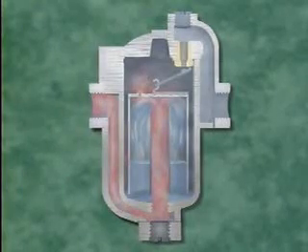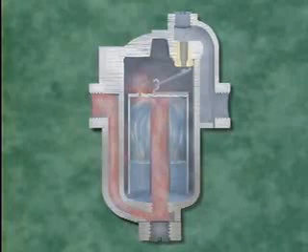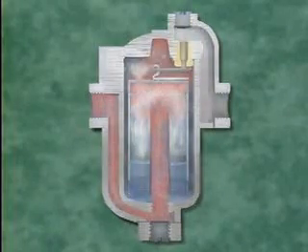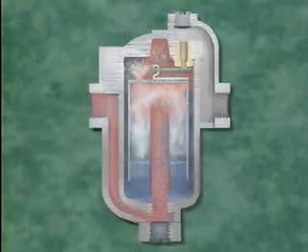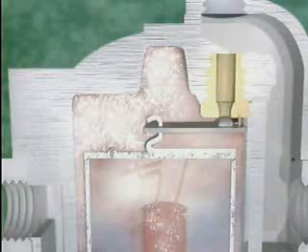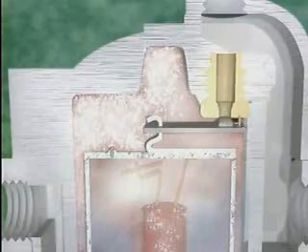When steam enters and accumulates to fill about 2/3 of the bucket, the bucket floats, and the trap valve closes, so no more condensate discharges. While the valve remains closed, air and non-condensable gases, which are less dense than the condensate, pass through the bucket's vent and collect in the cap area of the casing.